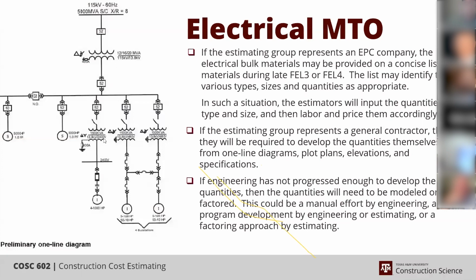It looks like 2,400 volts. Usually we wouldn't let anything over 480 be in the same MCC. It would be 480, 240, 120, and then the bigger stuff usually gets separated out and put into its own MCC with higher levels for entry and work inside of it.